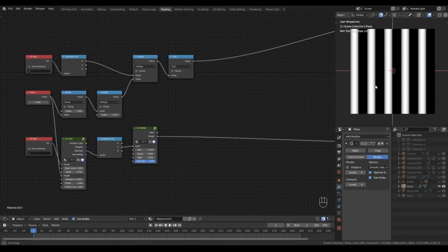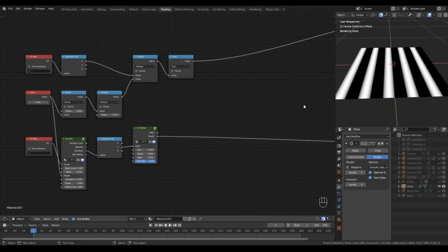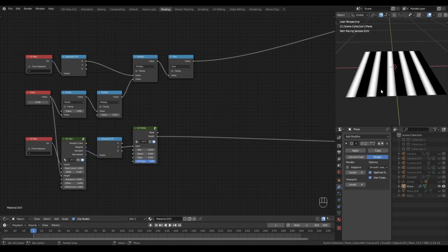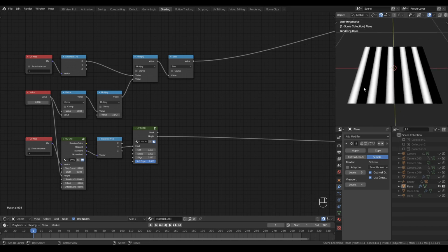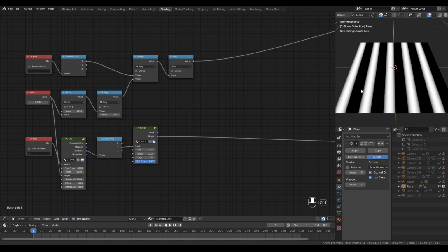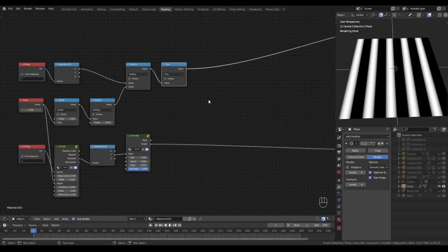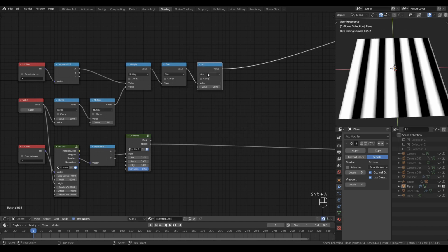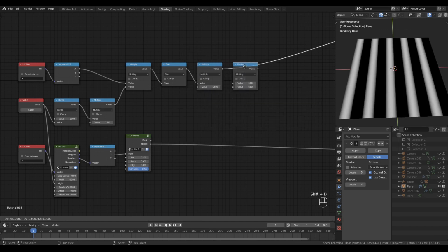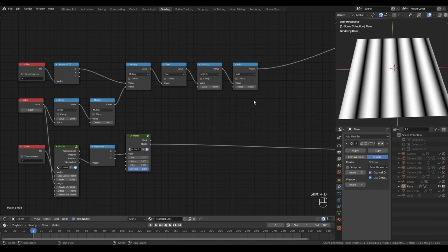Now then, let's address the height generated by our sine function right here. As I mentioned before, these values go into minus numbers, which will cause problems when we come to using material displacement. So I'm going to avoid that by transforming the -1 to 1 range of the sine node into a 0 to 1 range by multiplying by 0.5 and then adding 0.5. There we go.